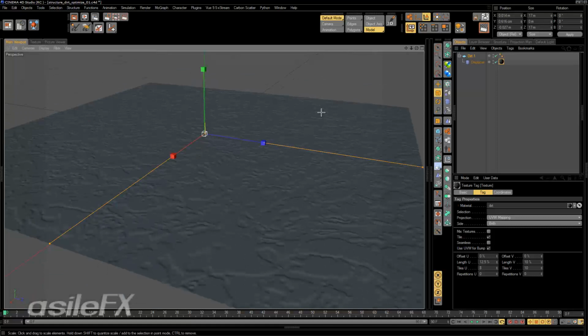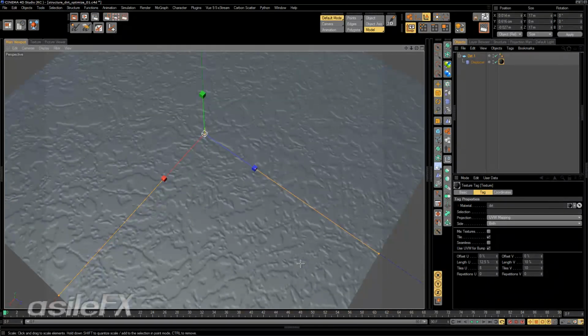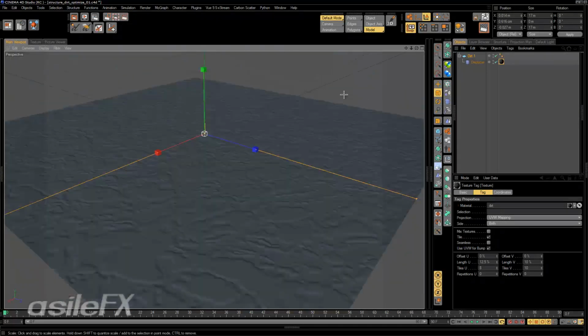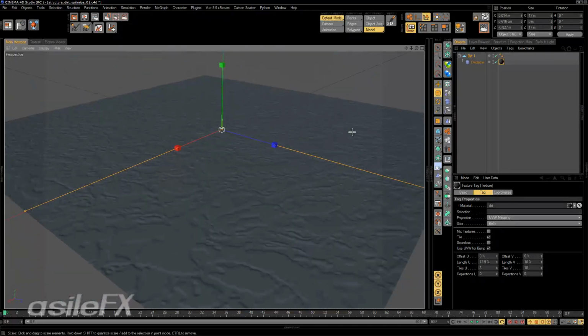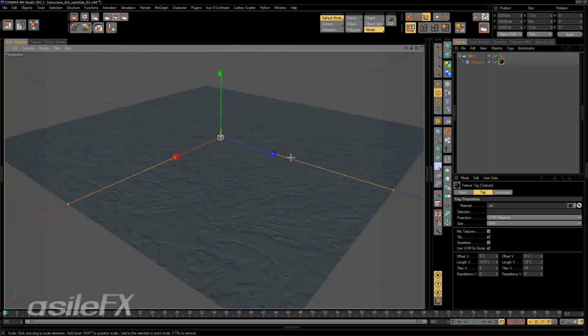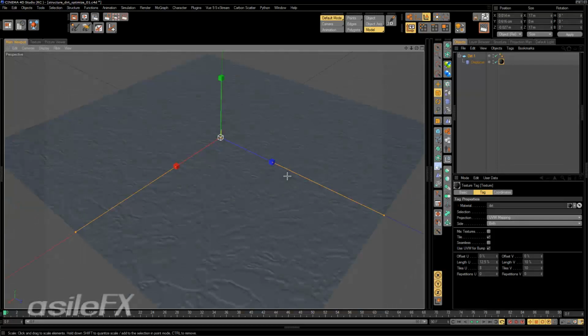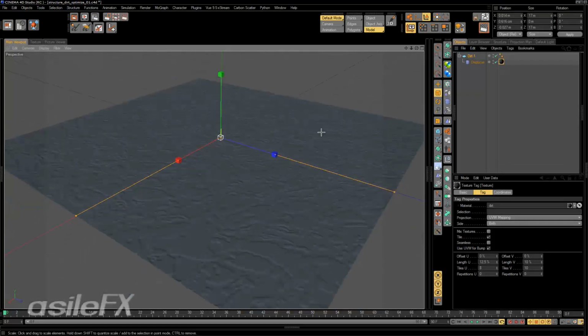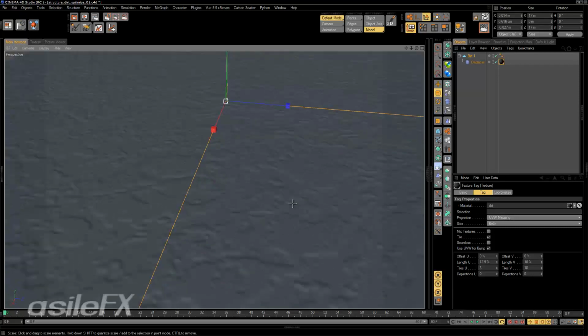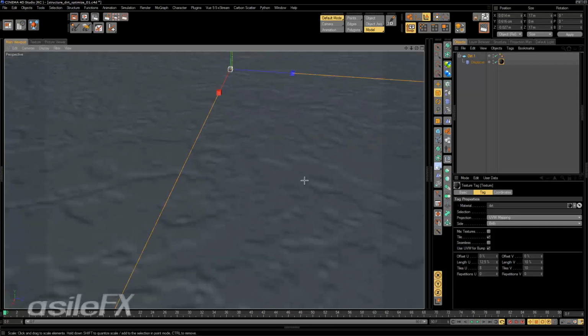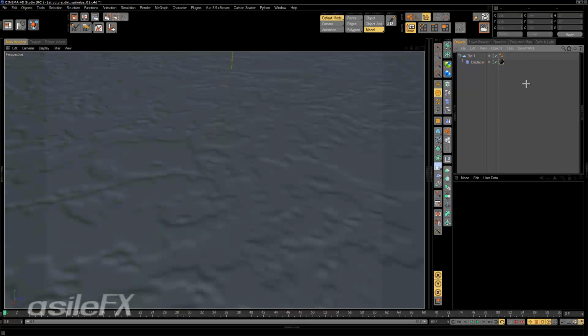So let's take a look first at some imaging techniques. We can render some materials to affect the ecosystem and not need all the geometry, and we'll be able to effectively populate onto a single polygon equal size, and then just use images that we can load into Carbon Scatter in the function editor to control position onto the surface, and also whether or not the objects will appear on certain slopes or altitudes.